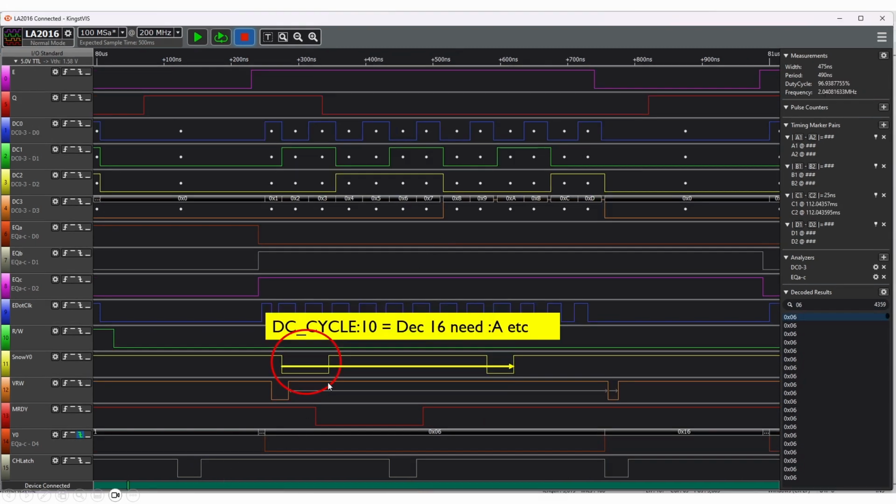Then there was another issue where, as I've already said, I was including some of the conditions in the programmable logic device configuration as 10 rather than A, and in fact that 10 has been interpreted as 16, and so that was messing up some of the configuration.